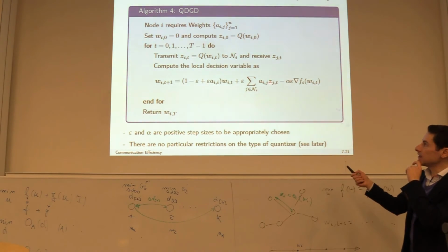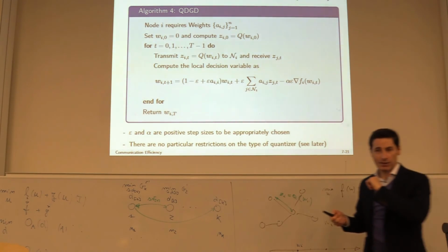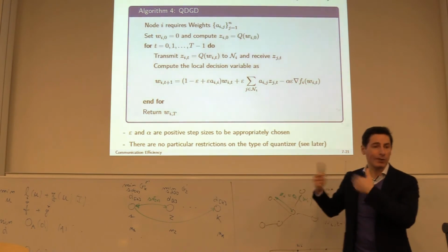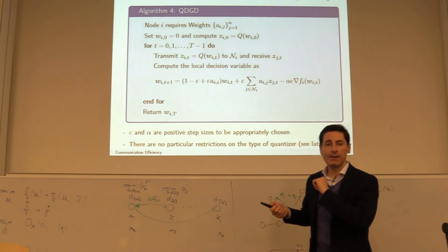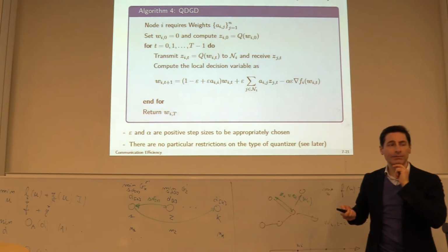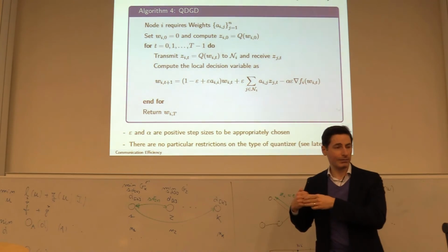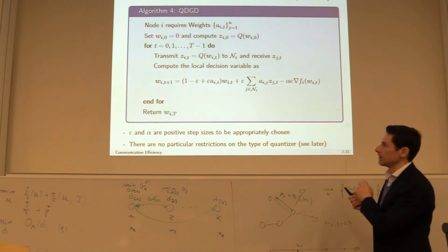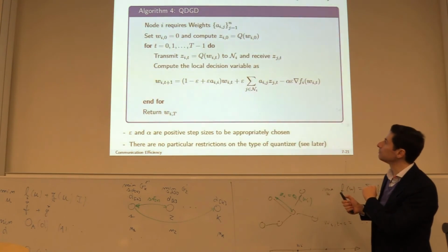We have the term Z, the quantization, that carries a quantization noise. And this quantization noise, in these equations, iteratively keeps accumulating. But despite this fact, this accumulation of quantization error will not diverge. Something that is not obvious. And that's the beauty, in my opinion, of the result that we have just seen.